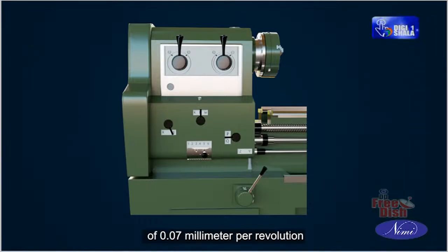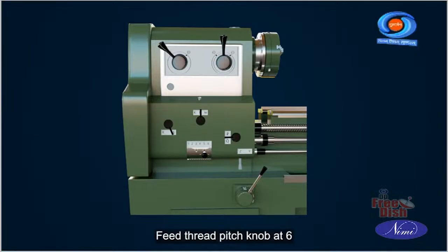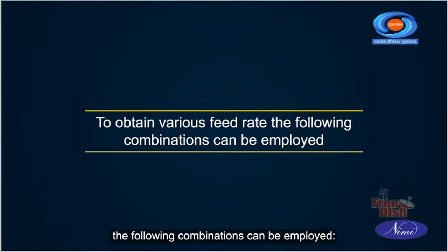To obtain a feed rate of 0.07 mm per revolution, set the tumbler gear to G. Forward feed direction in Z. Feed thread pitch knob at 6. Thread per inch lever to K. To obtain various feed rates, the following combinations can be employed.